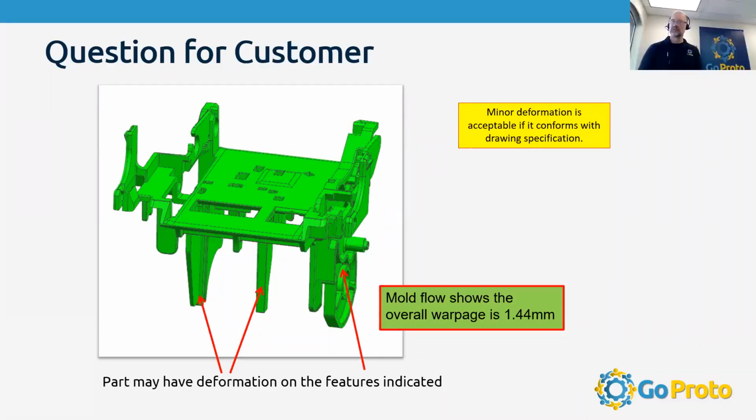Great question. Matt? Yeah, I prefer to get the models drafted. I think that helps everybody. I think it helps the customer from the standpoint of, if there's an assembly they're putting together, the drafted model lets them know it's going to fit. Then if we have to tweak it, you're only talking thousandths of an inch if we have to increase the draft for some reason.